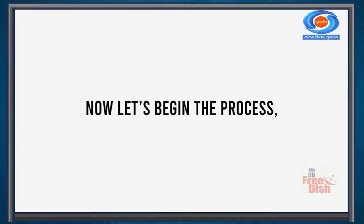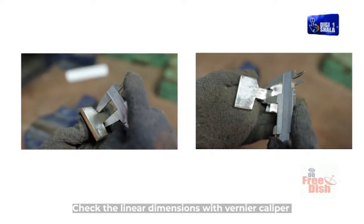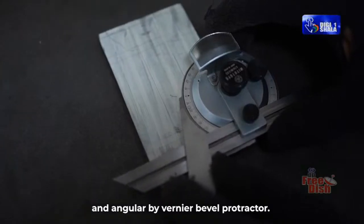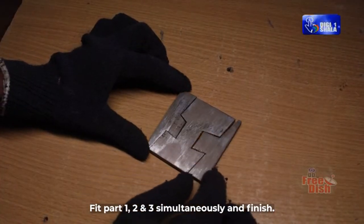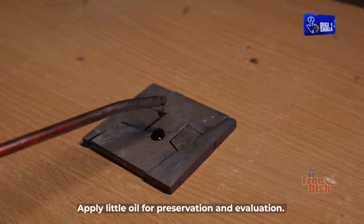Now, let's begin the process. Check the linear dimensions with vernier caliper and angular by vernier bevel protractor. Fit part 1, 2 and 3 simultaneously and finish. Apply little oil for preservation and evaluation.